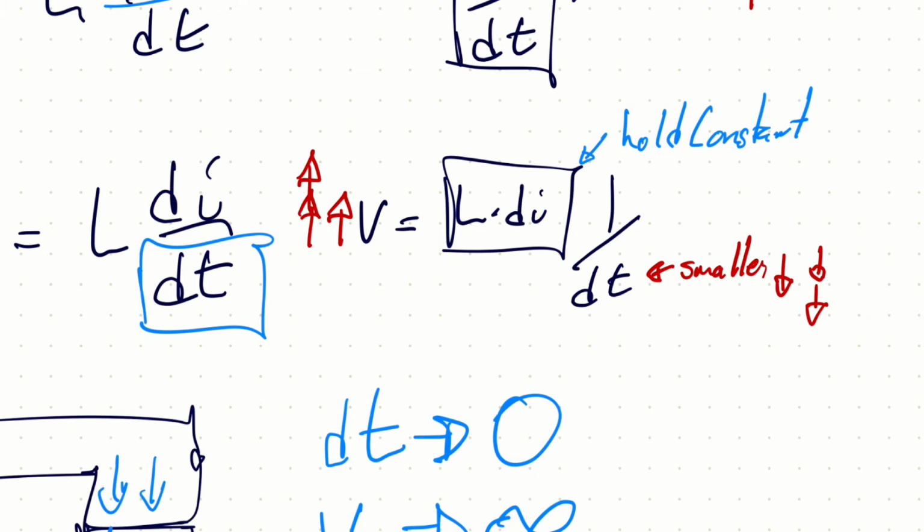But as dt gets smaller, you get this 1 over relationship. So imagine a tenth becomes 10, 1/100th becomes 100, 1/1000, 1 millisecond, suddenly becomes a multiplier times 1,000 when you're figuring out your voltage. And things happen in electrical terms pretty quick. It's only 16 thousandths of a second per cycle, and faults can occur in a lot less than one cycle. So you start to see dt is kind of working against us here. dt is driving big V's to start showing up.